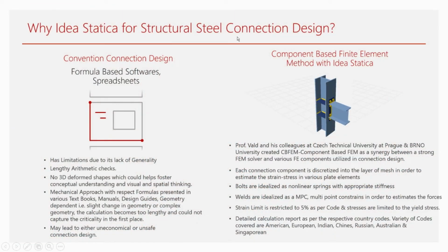So, why Idea Statica for Structural Steel Connection Design? There are basically two approaches: conventional connection design, and a component-based finite element method, which is implemented in Idea Statica. Conventional connection design is based on formula-based software or spreadsheets. You might be aware that there are certain sets of formulas which need to be satisfied, and the connection capacity will be the minimum of those capacities or checks.